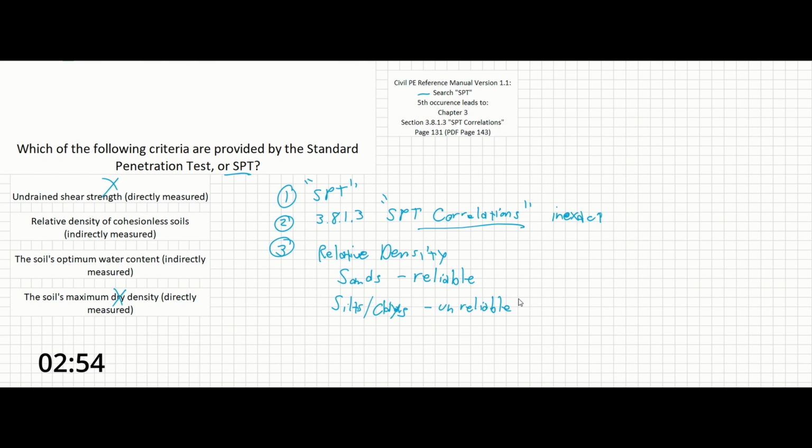So the one thing you would need to know in this case is that sands are a cohesionless soil, while silts and clays are not. That is to say, they have cohesion. So this is the one piece of information you would need to know to note the difference between a sand and a silt or clay as it pertains to this problem. And finally, based on points 3 and 4, I would say there's enough information here to strongly suggest that our answer is B.